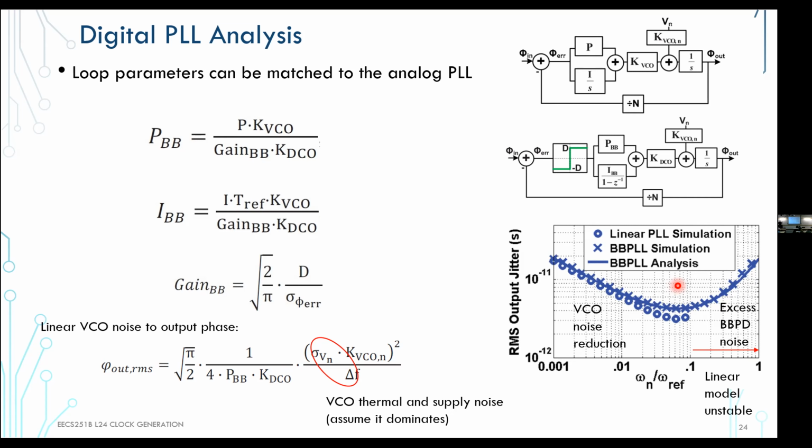So that's one way. If you look at where digital PLLs are developing, people design a higher resolution time to digital converter. That way it tells them more precisely where they are. So it can generate a larger error signal while maintaining the quantization error at that small delta, right? Because now you have many LSBs.